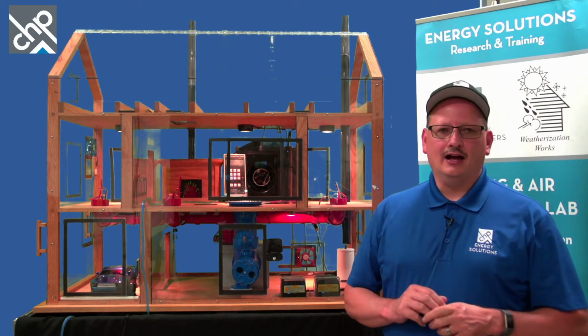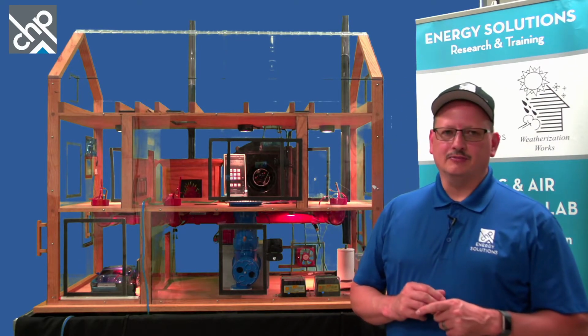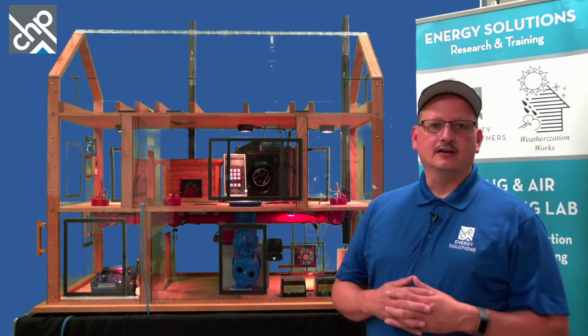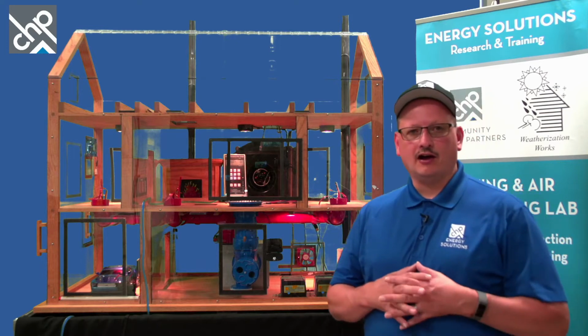And so I call this the house of pressure, where we can demonstrate house-as-a-system concepts, when you do something in one part of the house and it affects something else. And of course, in weatherization, we're always tightening the house up or adding insulation, making homes more efficient. But you may also have moisture and combustion to deal with as well. Heat, air, and moisture. We have another little house we use for that called the HAM house, and we do some demonstrations with that. But you have to keep all those concepts in mind.